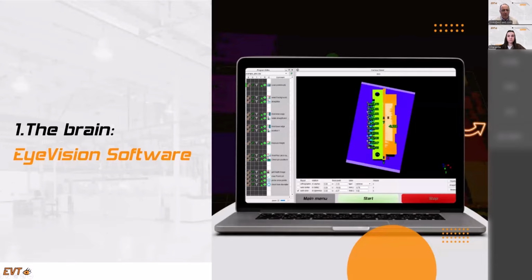so for you as a user, first of all, you have to think about what is the speed of my system? How many cameras do I have to connect to the system? And based on that, you can select, should I use USB, GigE, PCI Express, or Camera Link?